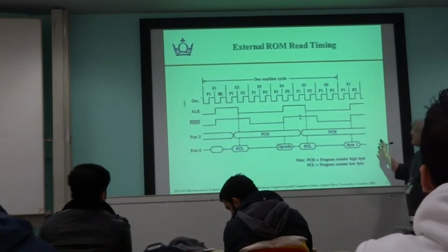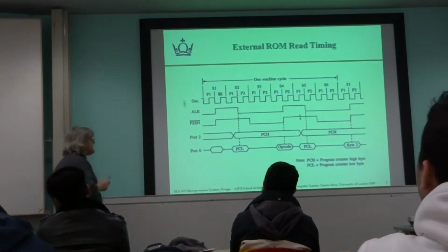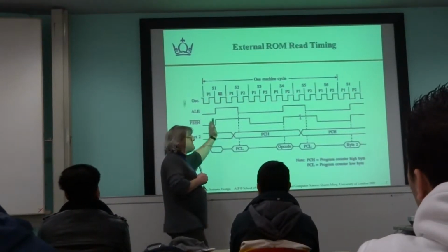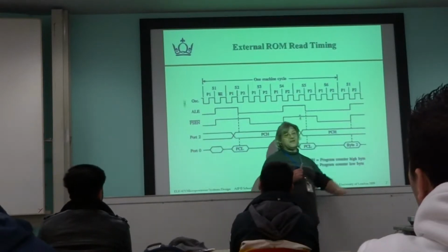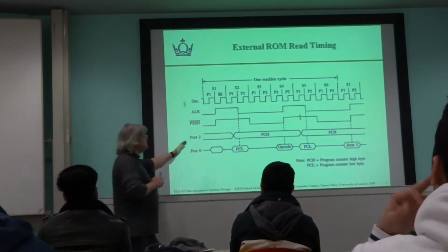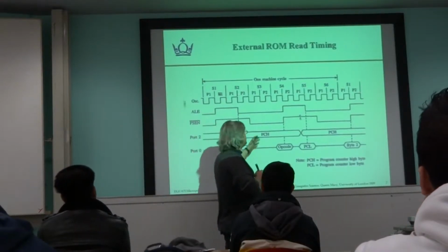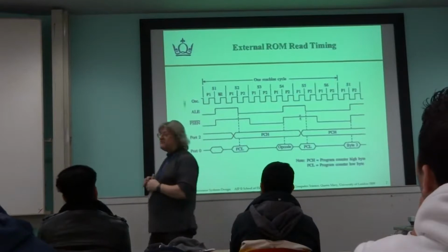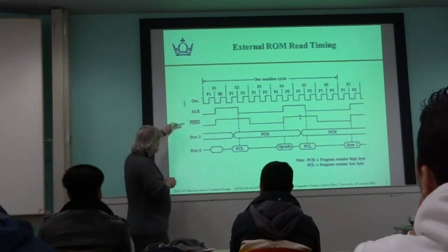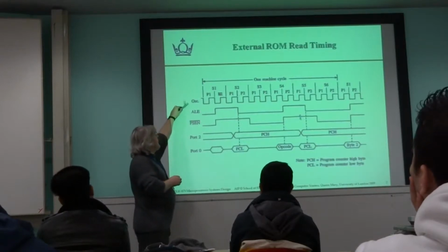In fact, this is now showing you the timing that goes on associated with that previous slide. And there was an exam question one year where this was actually put in the exam paper, and the students were asked to explain step by step what's going on in order to complete an access from the ROM. But I won't be expecting you this year to go through this in that detail, so you can probably breathe a little bit of a sigh of relief. So this is showing you the fetch cycle for fetching an instruction from external code memory. And you can see what's happening to port 0, port 2, the PSEN, the ALE, and the oscillator.